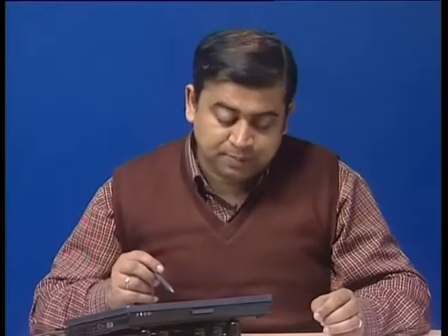In any case, any body in this universe, as you know, always prefers to go from a high energy content to a low energy content. Surface tension is a surface energy parameter, and so if the surface tension is lesser, the bubble would definitely try to go towards the lesser surface tension which is given by this temperature gradient between T1 and T2. So very interesting effects. In fact, there is a group at NUS which works on making these bubbles flow around in microfluidics based on this differential heating.